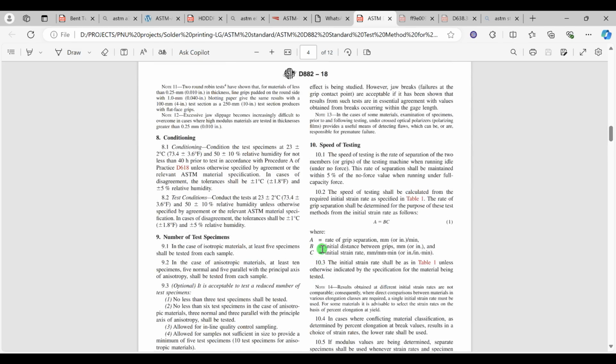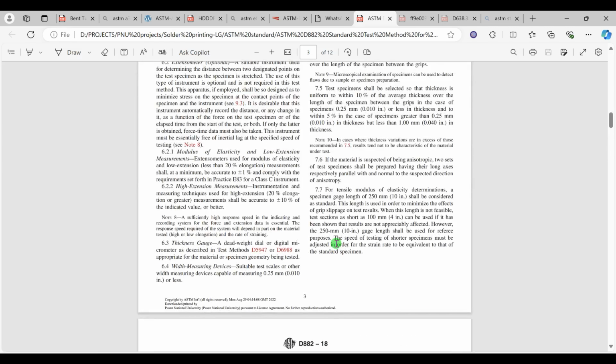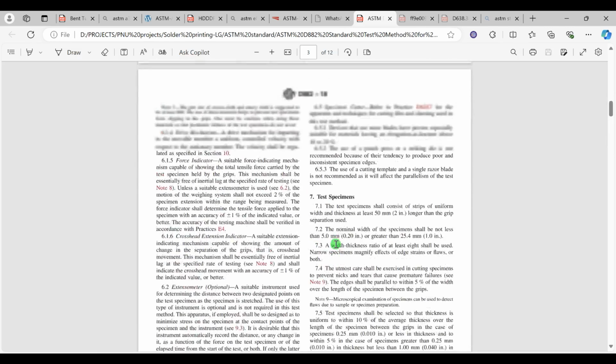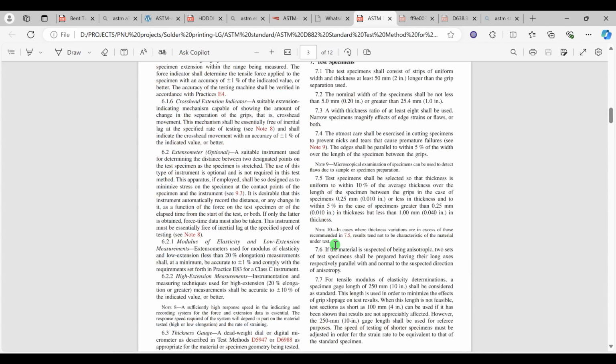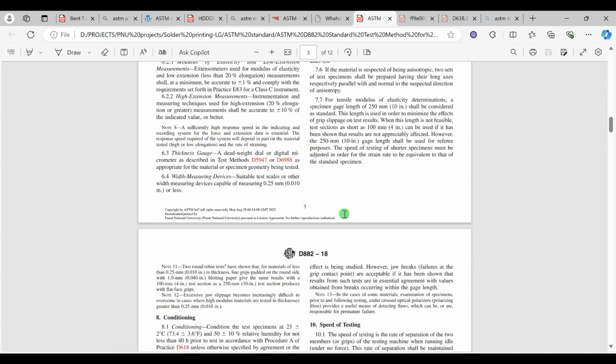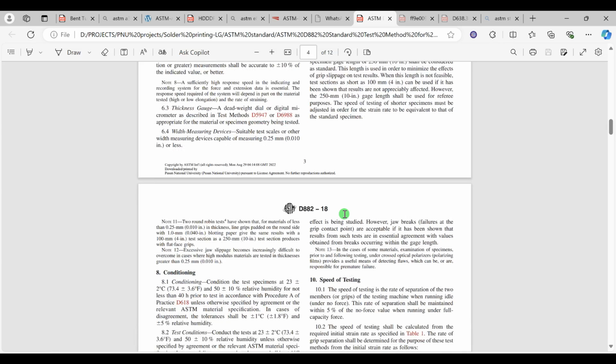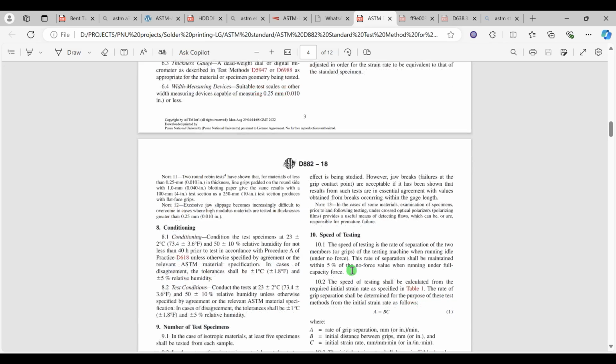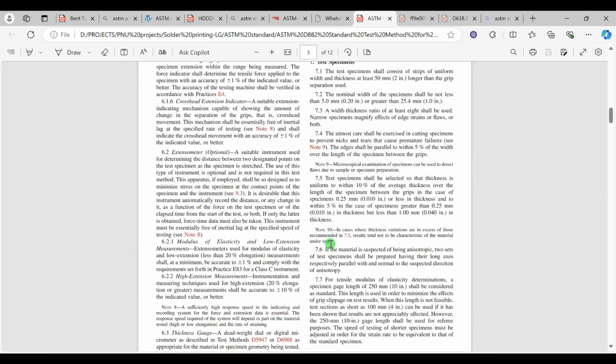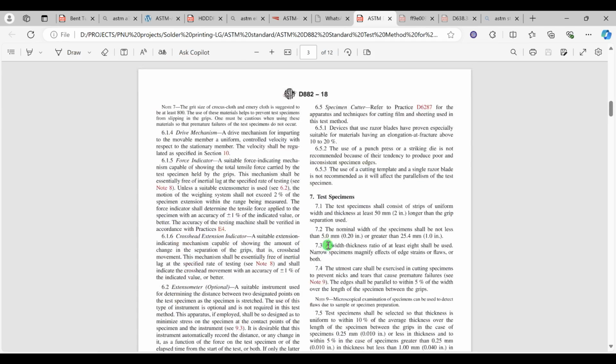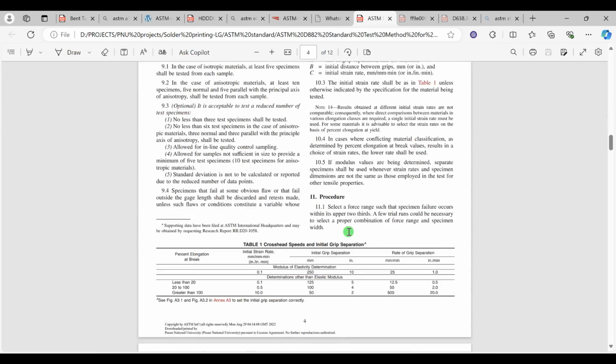And maybe in here you can find something related to gauge length or not, but since I read this standard several months ago, I remember that even the cutting method is mentioned in this standard, because it is a special material and needs some consideration for doing the test, such as testing speed, cutting the specimen, or even the shape of the specimen.